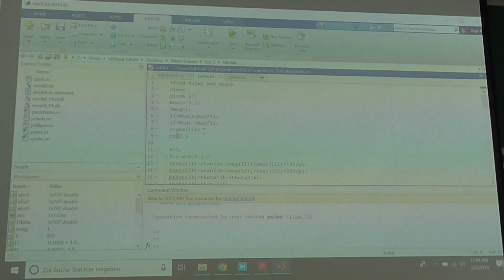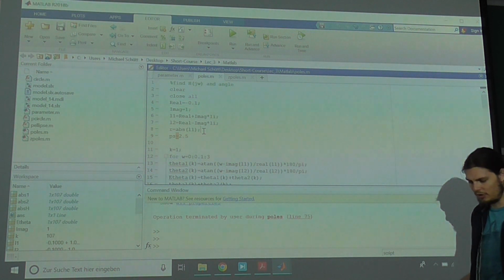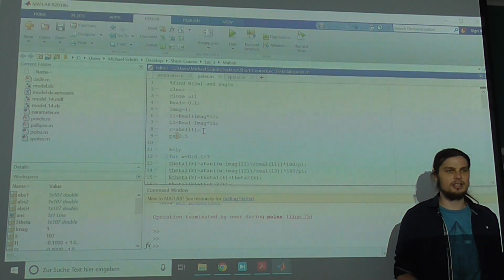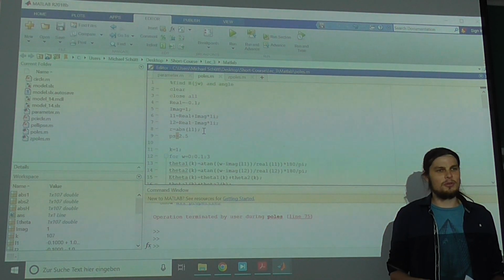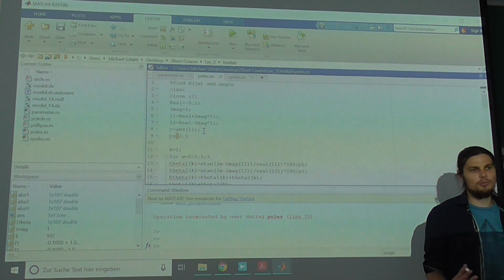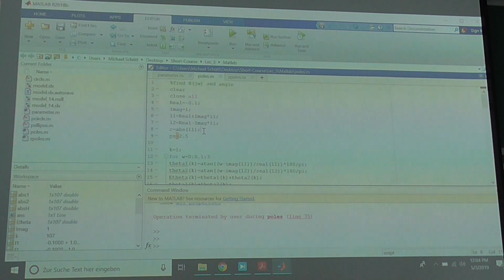Command tracking. You think command tracking, so that's what I think most people would say, right? We're most interested in what our commands will yield. But once we learn a certain trick, we should think maybe not really, right? What's the trick that showed us that command tracking is really not our state feedback controller's job? Feed forward, correct. Command tracking we do via feed forward. If we have a feed forward, we should get the right results.